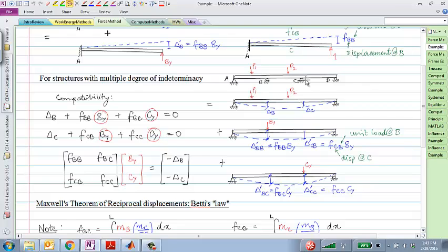If you remove the center 2 supports, it's 2 degrees of indeterminacy, which means that you would need 2 equations of compatibility, which also means that you would need to solve for at least 3 flexibilities, and at least 2 real displacements, right? That's 4 or 5 sub-problems at least, right? So that can be a lot of work.